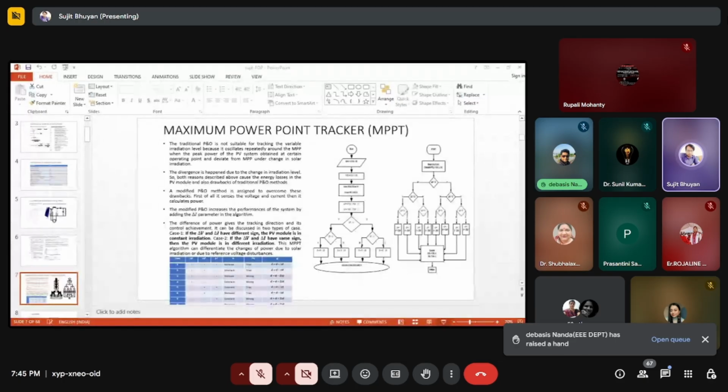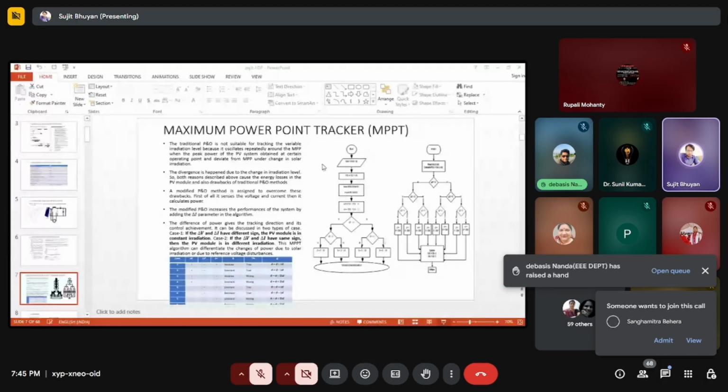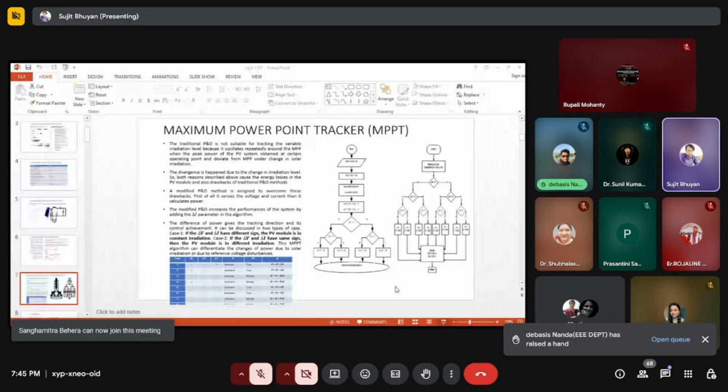We are using the voltage source converter control. So here, I have given you a little bit of an idea about the voltage source converter control. Here you can see the whole structure, the part below the PV array: inverter and filter circuit. The whole part is voltage source converter control, which is basically divided into two parts: a voltage control loop and a current control loop.